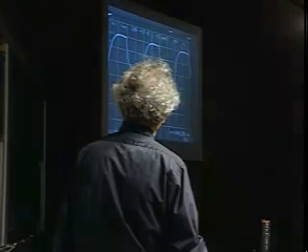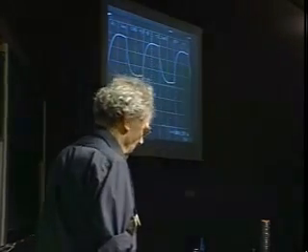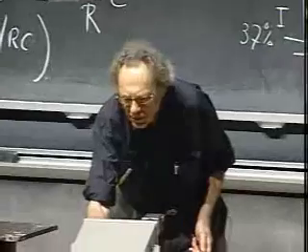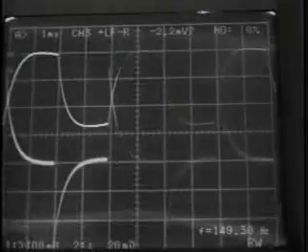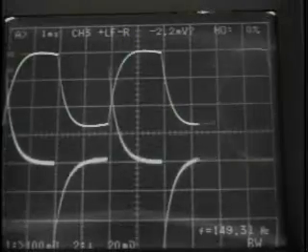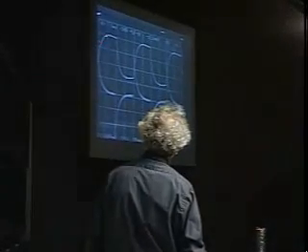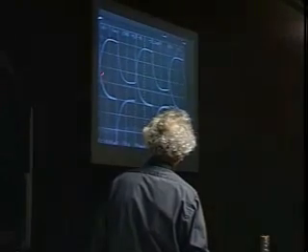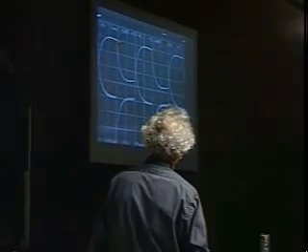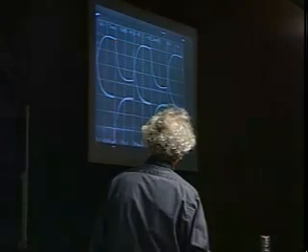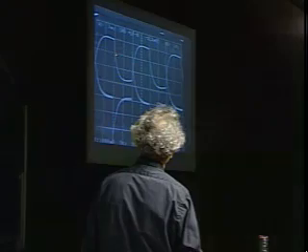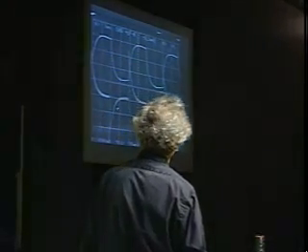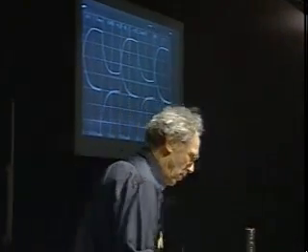And then it's charging up again and discharging. And now I can also show you the current. You see it on the same plot. As the capacitor is charging, you see the current. It's high. But by the time that the capacitor is fully charged, the current is 0. But the moment that I throw the switch to position 2, the current flips direction, becomes negative, and then as the capacitor discharges and heat is dissipated in the resistor, ultimately the current again will become 0.